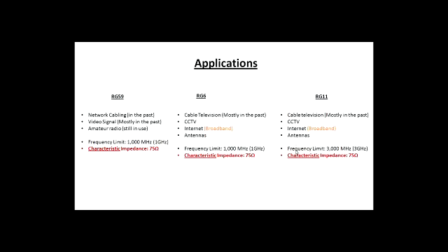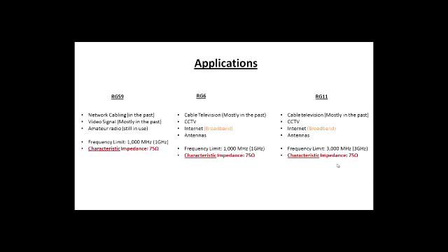Because of the greater physical parameters, there's a thicker cable being used, which means less resistance, and there is a little bit more separation as far as distance. So all those factors contribute to a better frequency limit, better bandwidth. So it's 3 times as much, 3,000 megahertz or 3 gigahertz.